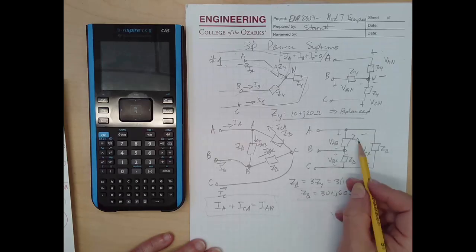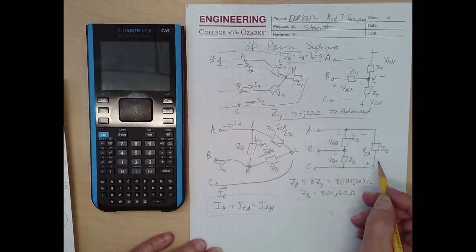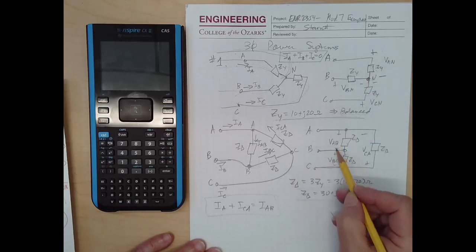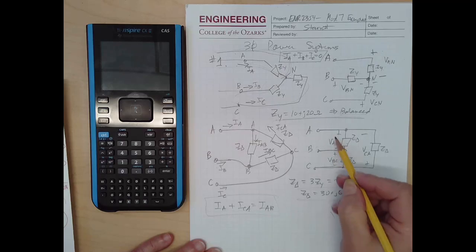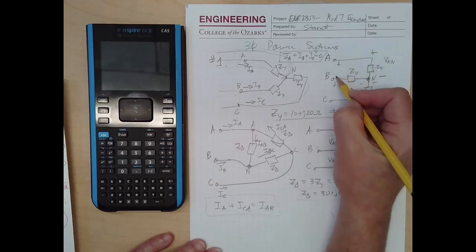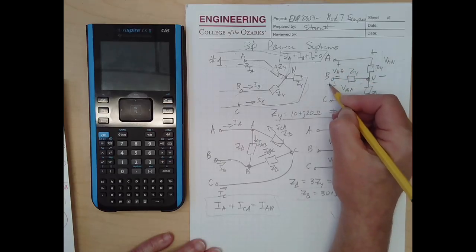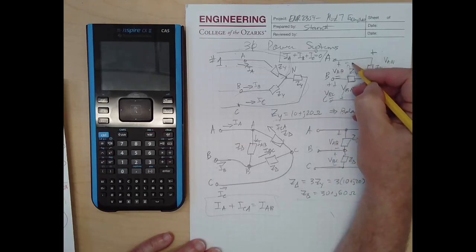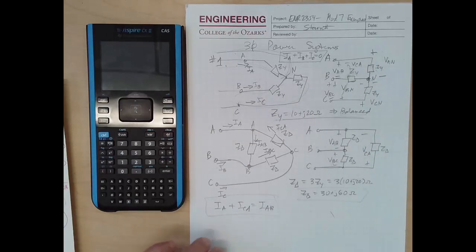All right, and over here we can also put the line voltages. These would be called line voltages or line-to-line voltages, the voltage between the lines, whereas these are line to neutral voltages. We have line voltages over here. We've got VAB is also here, VBC, VCA going back up. We can also define them in a Y. And that's probably about enough names.